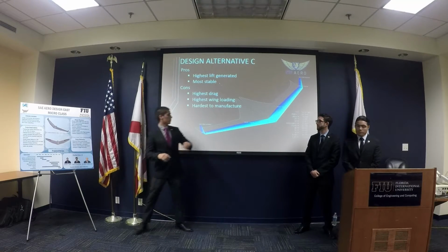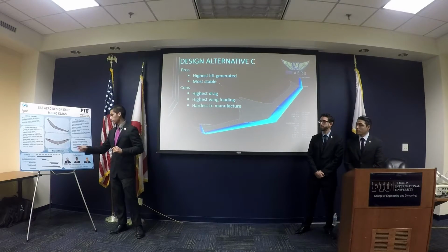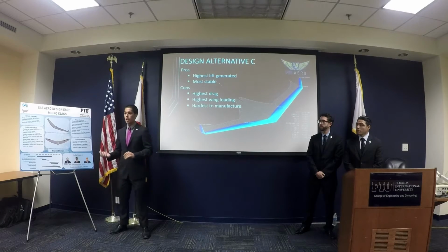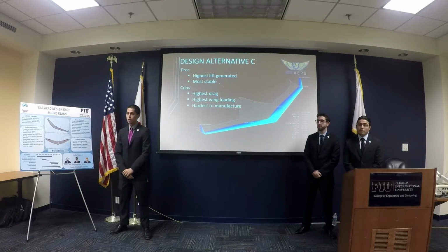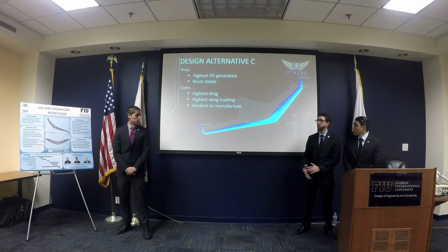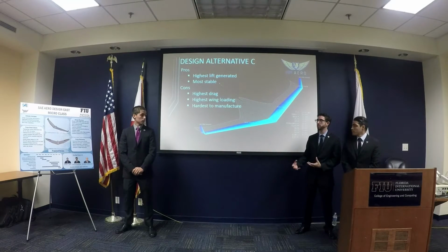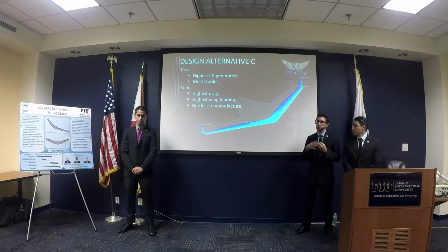So on the wing itself, where it connects to the fuselage, we run the wires internally, and we have two contact points for the servos on each wing. So all we have to do is snap and play, and we don't worry about having to plug in cables. But either or, whether it's cables or whether it's contacts, these servos are going to be connected to the main power source, which is located on the fuselage. So I want to build into that and say that we definitely want to do away with the wires because they add unnecessary weight in our case, especially connectors. We're really looking into some sort of integrated banana or maybe a DIN type connector that has that compression when you connect them together, so that they won't come loose during vibrations or forces or something like that.